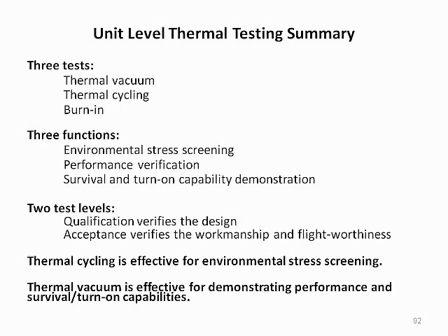Thermal cycling, with its rapid temperature transition and many cycles, is effective for environmental stress screening. Thermal vacuum, with its vacuum environment and temperature cycling, is effective for demonstrating performance and survival and turn-on capabilities. We will now proceed to the topic of development testing.